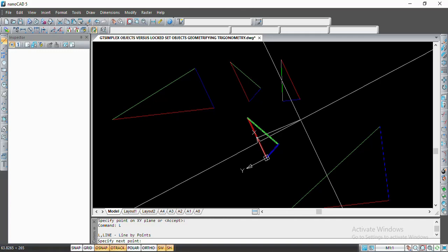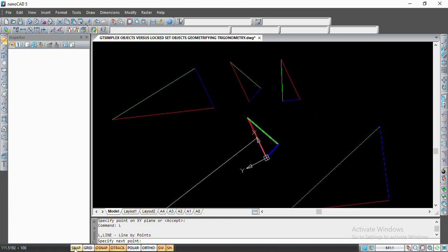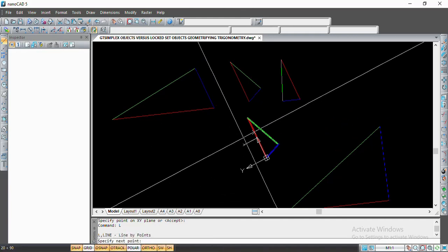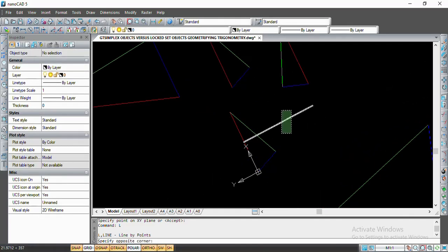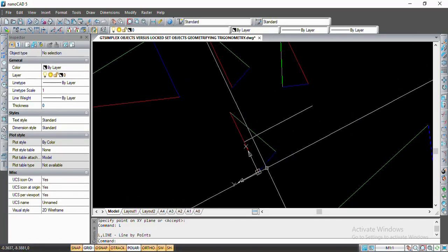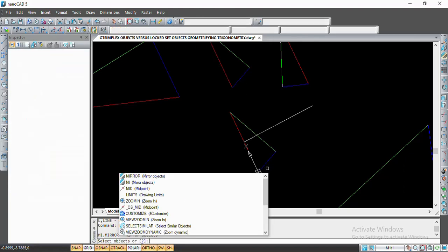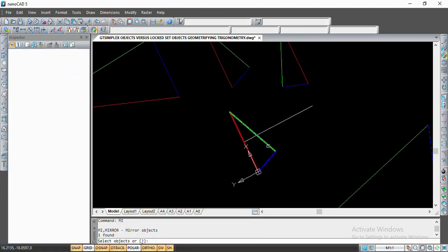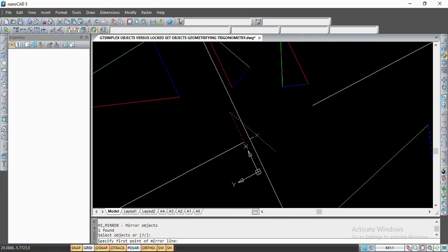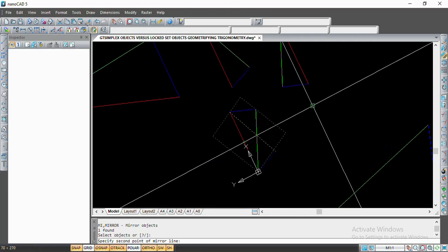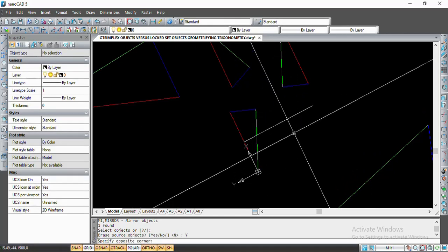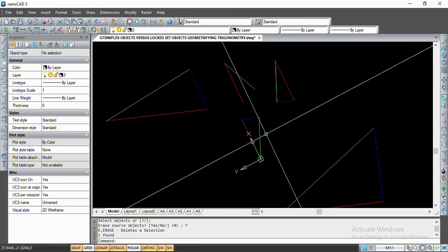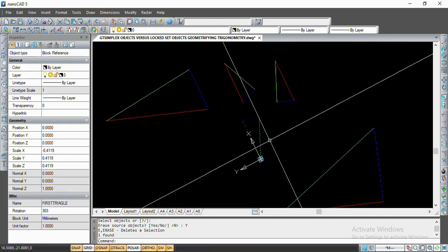If we take the snap and if we take the ortho, then the orthographic line is drawn here, and this is the mirror line of this constructed line segment. If we do the mirror, now mirror is the affine operation, so the coordinate system is immaterial for that, and I will erase this. So the mirror line is this one, and now one symmetry is formed in this way.